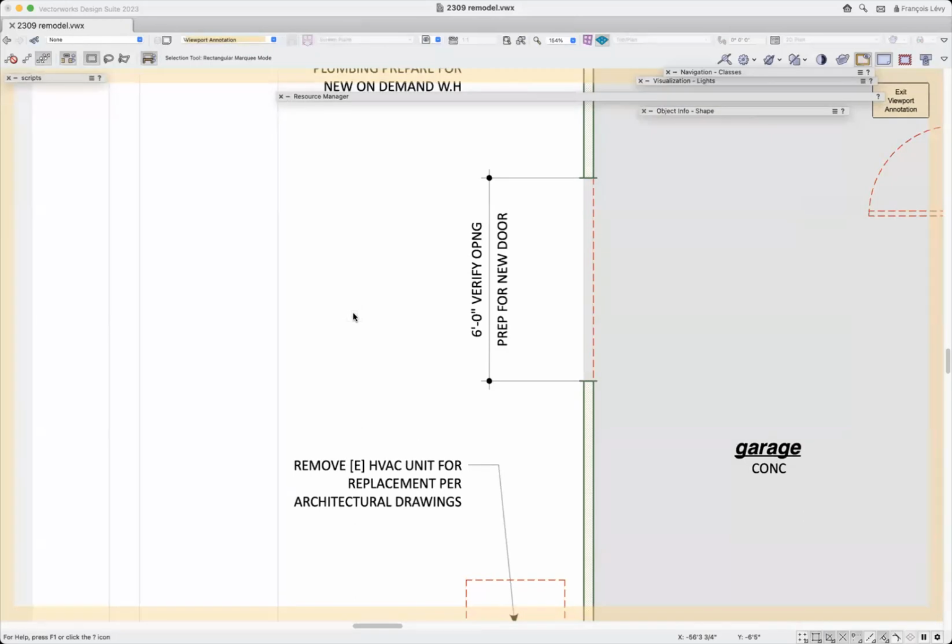And obviously, if that's a load-bearing wall, which it likely isn't because it's on the gable end, then I probably need more than just the rough opening, the 6'2" or whatever. I probably need another 6 inches at least for a couple of studs on either side. At that point, what I may be doing is making that opening considerably larger, drawing a wall in there that is the width of the unit plus the rough opening plus whatever structure I need to support the new header, and also account for the header height above, right?